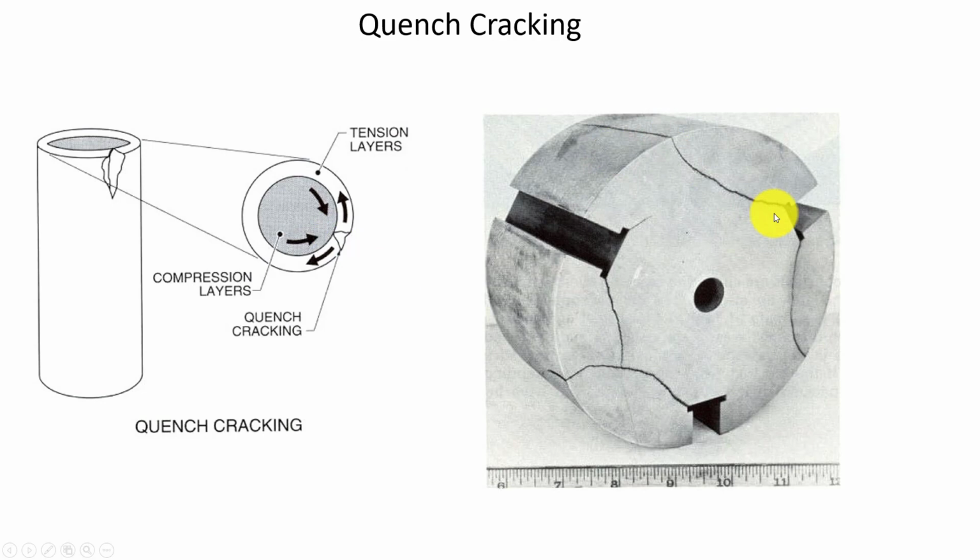Now, these are all big cracks, and yes, you can see these, okay? We can see these big, beautiful cracks. And I want you to look at this part. See this transition from this area right here? Those stresses localized at that concentration point and cracked out. So this part would be very susceptible to quench cracking. So changes in cross section, or if we have a thick and a thin section, yes, we can have quench cracks develop in those parts really, really easy.